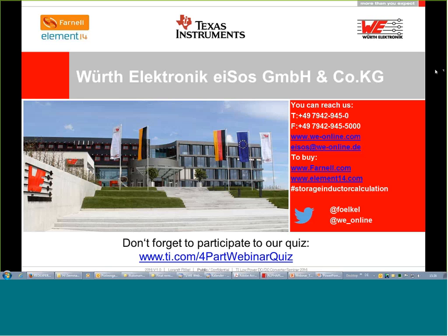And I put that also in the video. It will be available soon on our website because I was so impressed. I said, okay, I have to share this impression, because this is something really nice, which I fought with almost 20 years ago as a design engineer. When I made DC-DC power supplies, I had that problem, since efficiency requirements were already very high at that time. Today, if you build something, you need at least 85–90% efficiency as a minimum, I would say, if you build a DC-DC converter now.